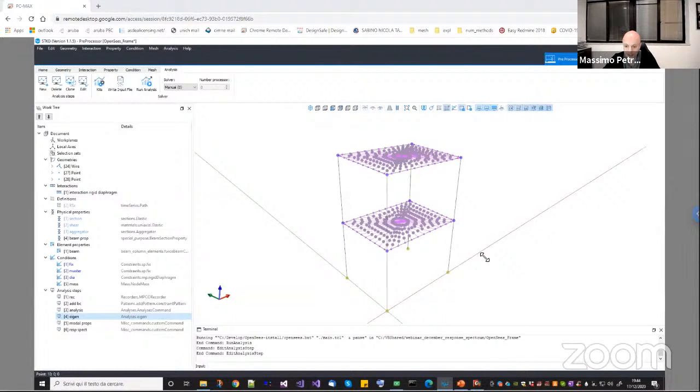If instead you do the eigenvalue analysis on a later stage of your model, let's say you push your model a little bit, one of the trusses goes in tension, so it has a 0 tangent stiffness. If you do the eigenvalue analysis at that point, then it will correctly take into account only the stiffness of the compression truss. But this is a kind of complicated topic. I will give you an introduction to this one at the end of this webinar.